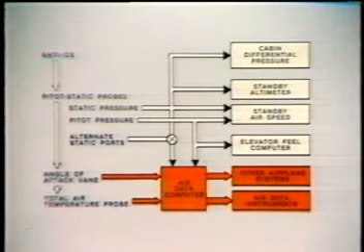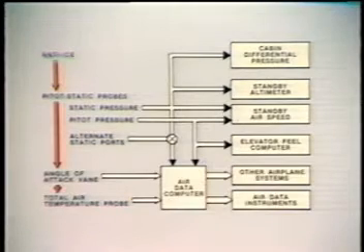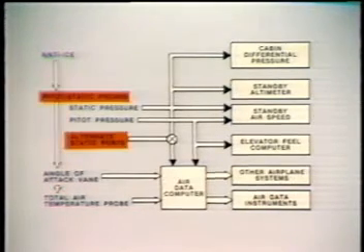This includes the electrical signals coming into the air data computer and those generated by the computer, which are used throughout the airplane. The electrical portion also includes the probe anti-ice circuits. Each of these will be examined in more detail, starting with the pneumatic portion, followed by the electrical signals, and finally by the heating circuits.